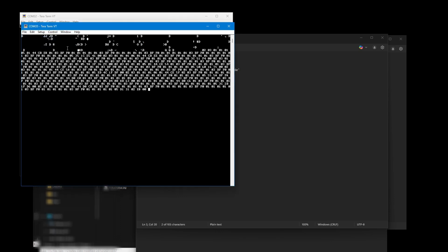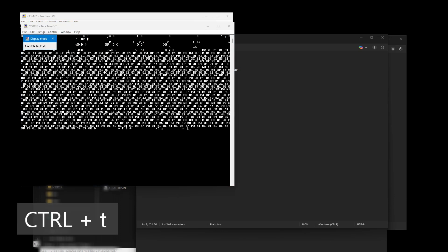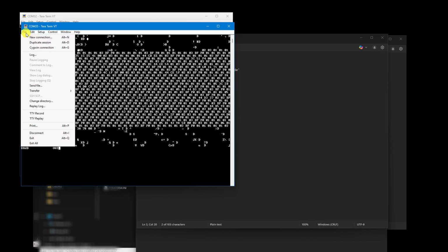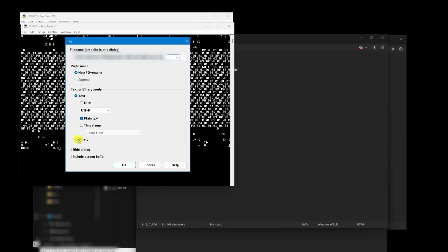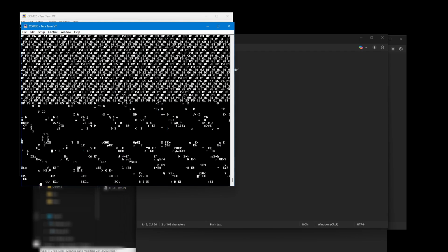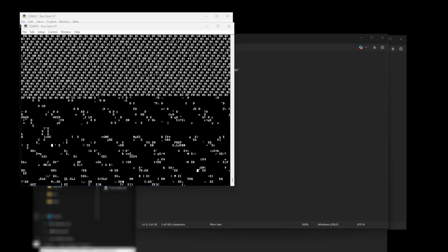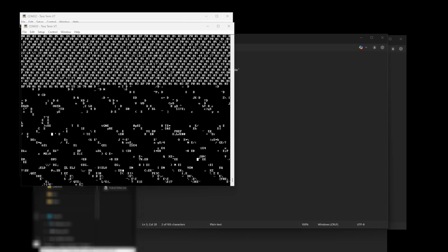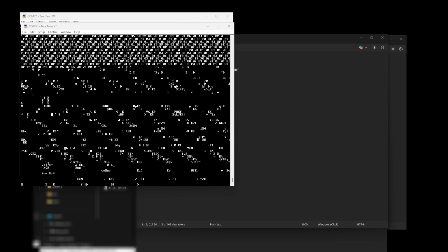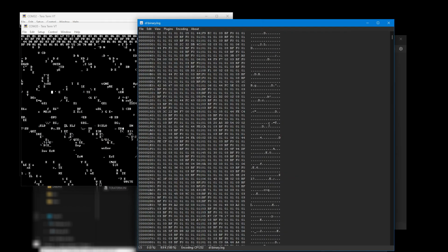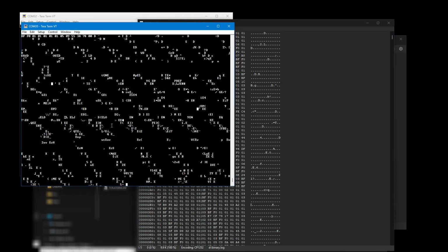And now you can directly set Teraterm in the mode you want with the hotkeys you picked earlier, and you get feedback about it. Finally, note that if you just need a file of the communication for later analysis, you can also use the built-in logging tool to log it into binary form. That way also allows to look at the HEX codes with a suitable viewer, but it will still be beeping all the time, so switching to HEX mode remains useful in my experience.